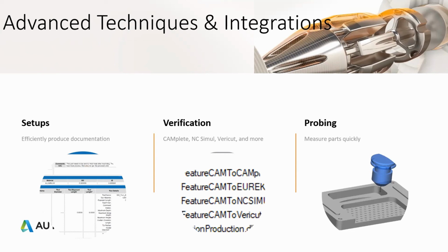So you can do everything from setting your setup in a specific location, updating the location of that setup. You can update tool lengths after probing the depth and seeing if the feature is where you expect it to be. If not, you can update the tool length offset. You can also just take measurements to verify the parameters, setting the tolerances that you want. And if there are any issues, you can even prompt the process to stop, or you can just print out the results, whatever it is you need for those.